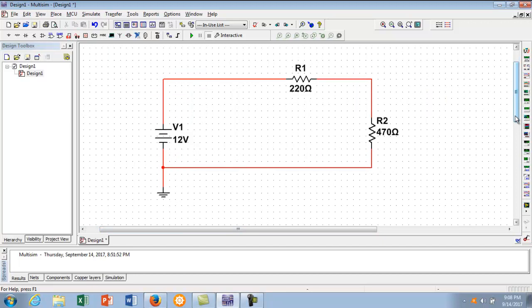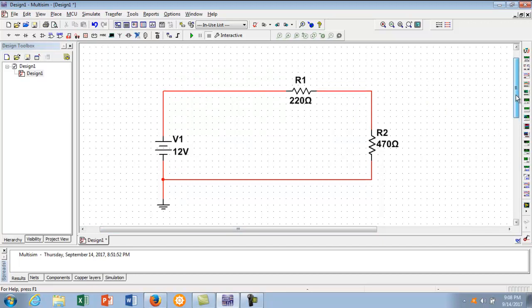Right now, though, there's not a whole lot to see as there's not a lot going on. If I wanted to begin the simulation, and indeed Multisim is a simulation package, once you design something, once you lay out a design, you can start the simulation by hitting Run, F5, the green icon. Some of them have a switch icon here to turn it on, but more often than not, the green tab will run. Let's click Run, see what happens.